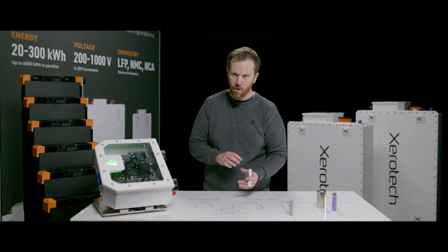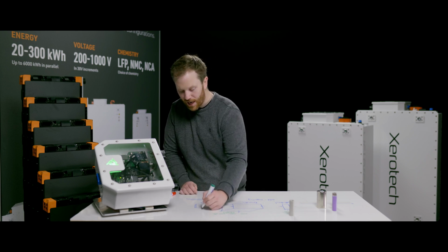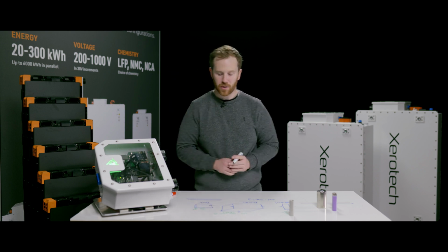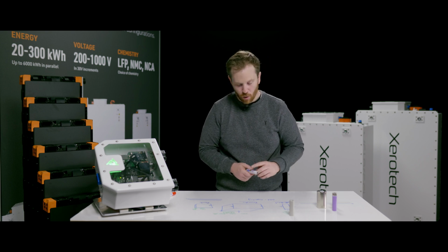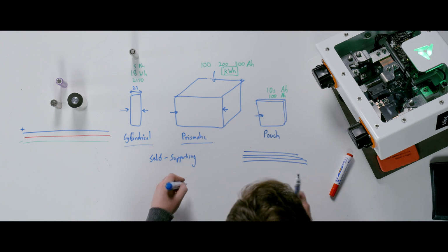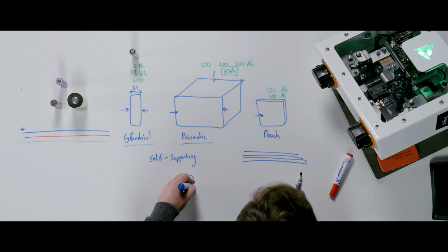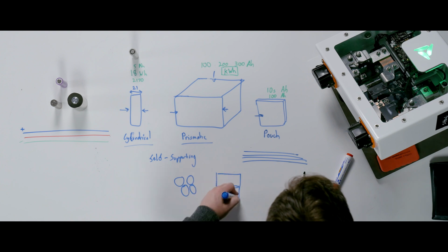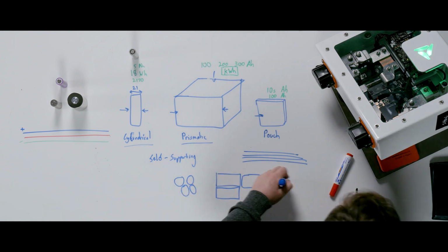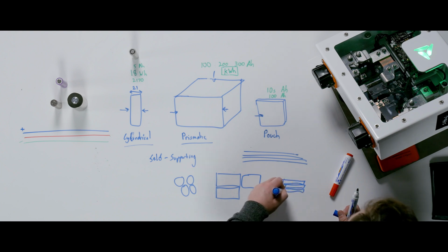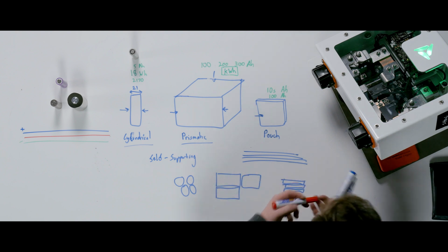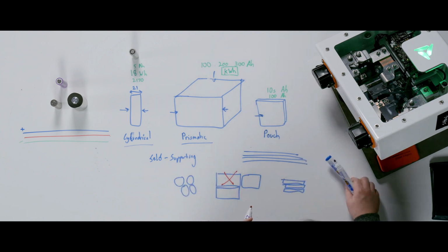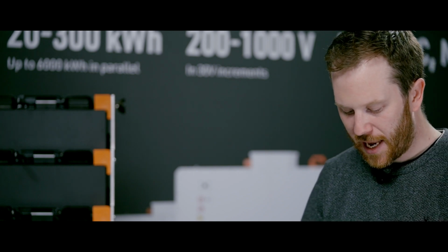Likewise with pouches, they vary, but they can be quite big. They could be tens of amp hours, if not even 100 amp hours and above for large pouch cells. This is a lot of energy. So in the event of a thermal runaway in a real battery pack where you've got lots of cylindrical cells packed together or lots of big prismatic cells packed together or even pouch cells, if you've got large units of energy and if one of your units of energy fails for whatever reason, it is extremely difficult to contain that energy.